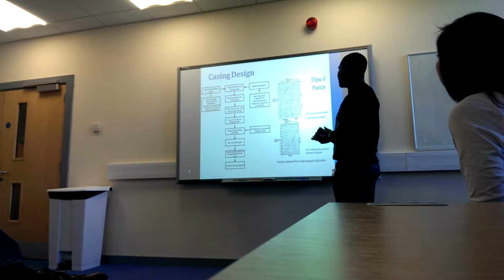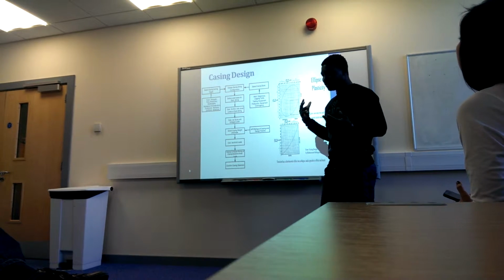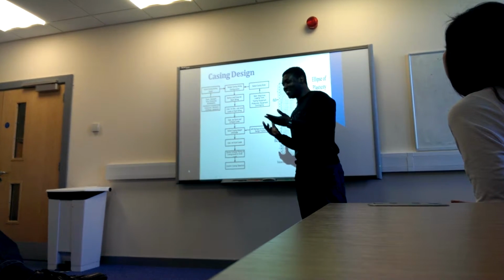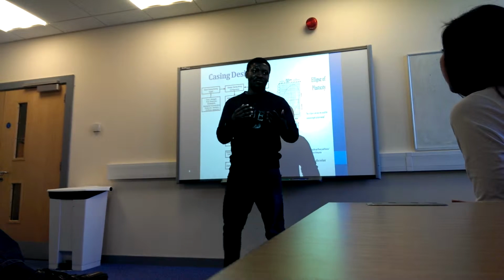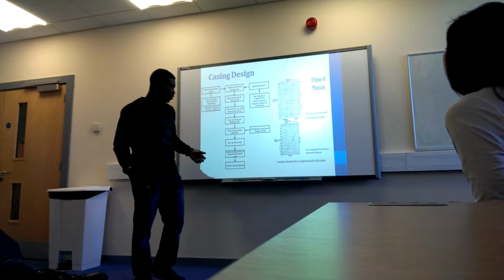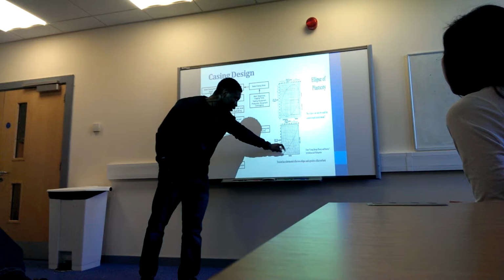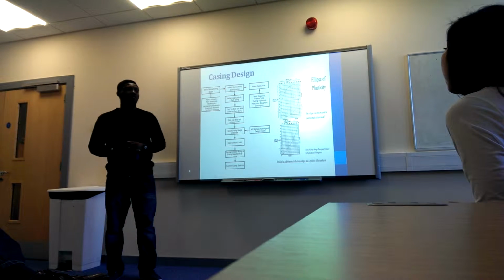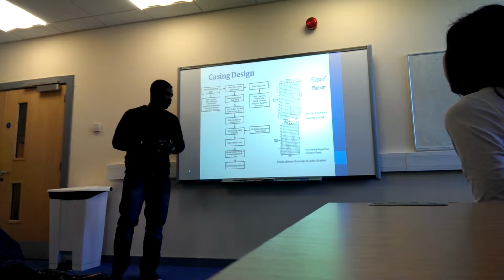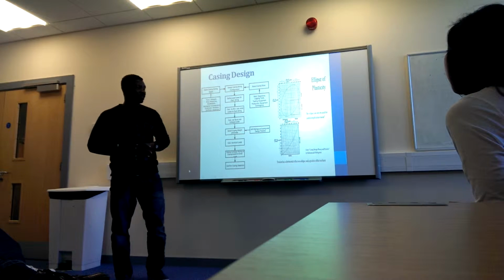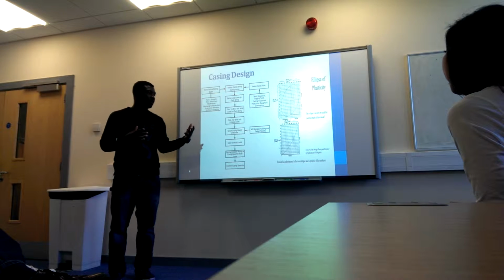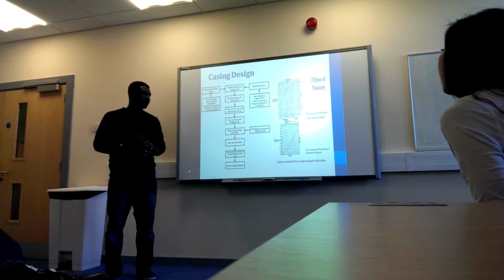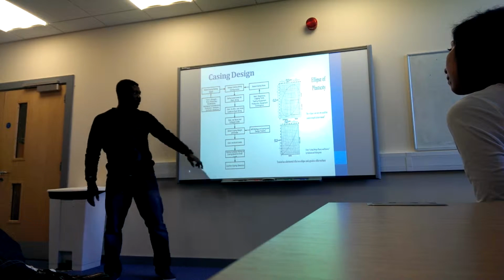Here you can see the ellipse of plasticity, which was used in measuring the axial stress of the pipes to see if they could withstand the formation pressures. And also we can see another graph here that compares the tension with the collapse pressure, to see how with increased tension there's a possibility of fracturing or disrupting the pipe.